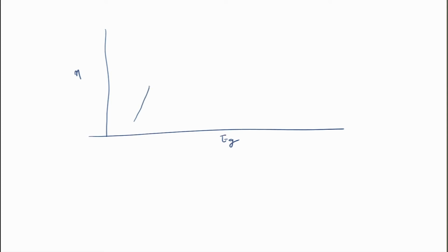So, next I would just again draw the curve, as we saw last time. This is the efficiency curve as a function of EG, and this curve goes something like this, and this maximum efficiency is about 33%, and this falls around the band gap of nearly 1.4 eV.